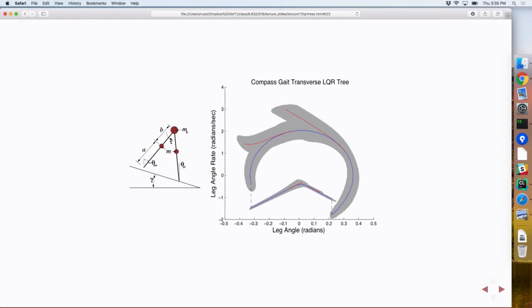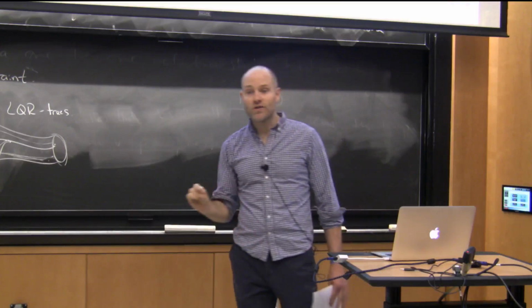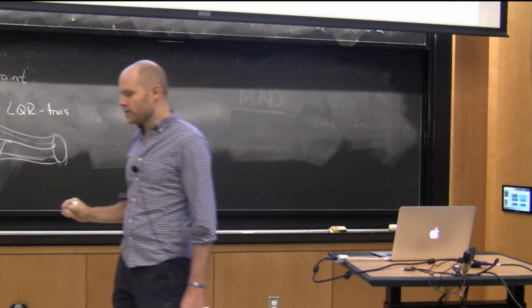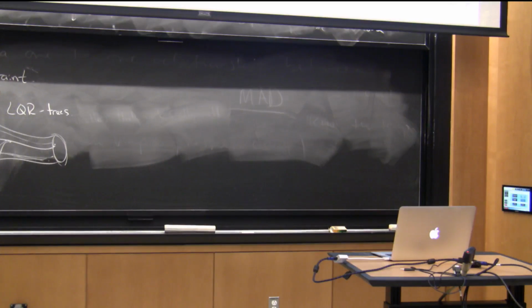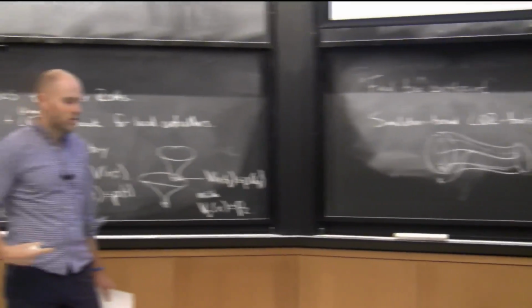The picture on how you stabilize a walking robot works too. You can do the region of attraction using transverse linearization. Now it's a transverse coordinates Lyapunov function that computed the region of attraction of the initial limit cycle. And then how do you design the recovery maneuvers, right? The nominal limit cycle stabilized with LQR works for only a relatively small set of initial conditions. At some point you have to do something different.